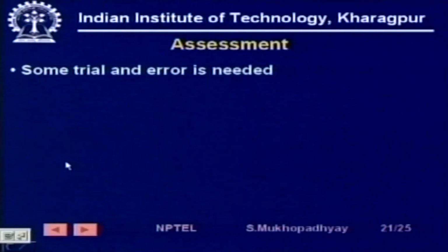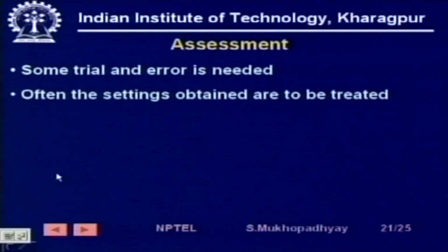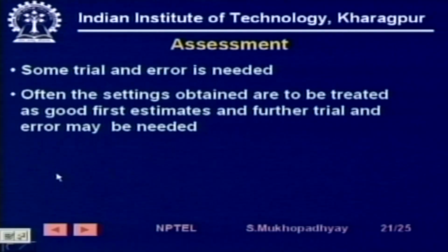So what is the assessment of these closed loop methods? Some trial and error is needed, and often the settings obtained are to be treated as good first estimates. After that you may like to tune a little bit and see whether you are getting still better performance, then you should select those values.